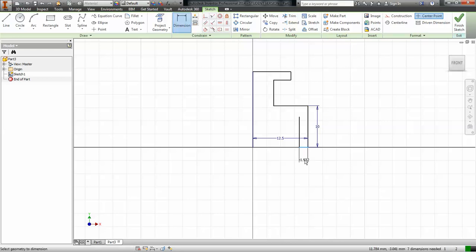And so, actually, that's pretty close. I was going to say 2.2 was the thickness. So I'm going to say 2 millimeters is the thickness of my cap. I click OK. And we're going to just kind of stick with that. So we'll keep drawing this. So go there. Now hit escape.